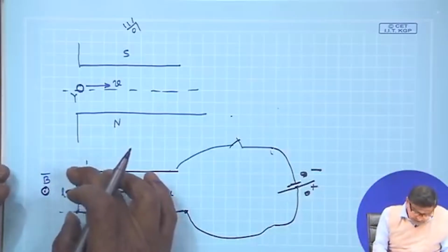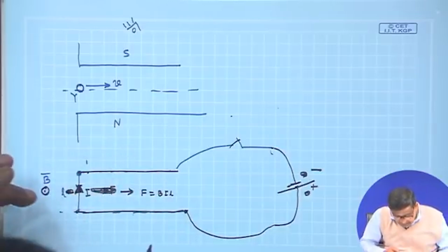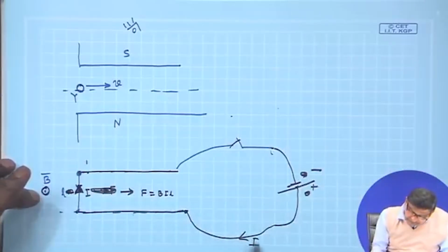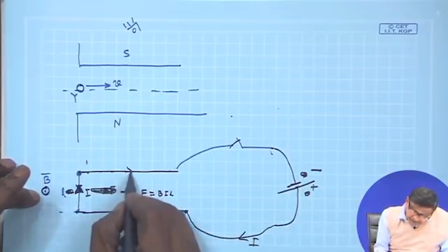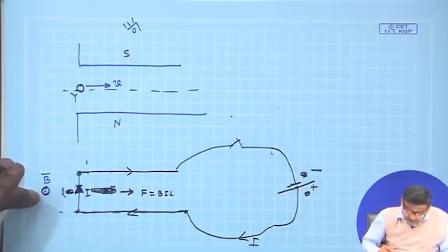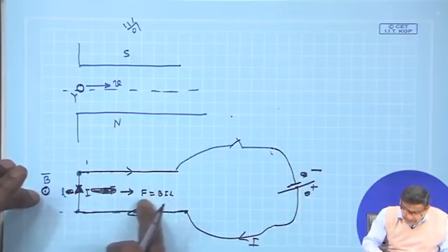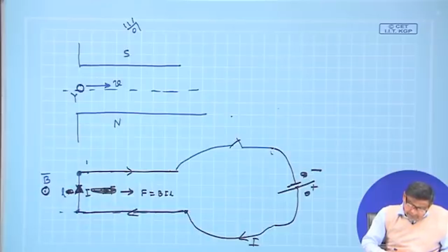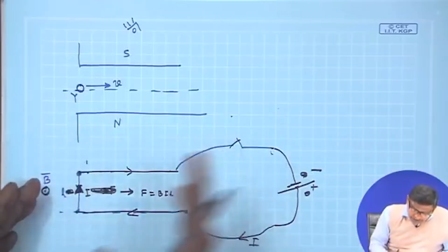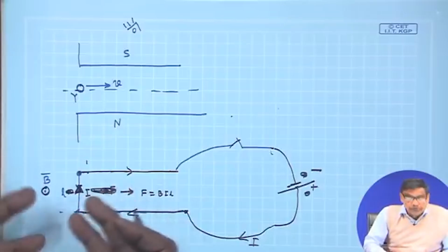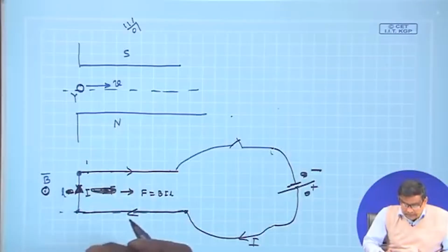Therefore, the conductor was stationary. In the presence of a magnetic field, you pass some current I, it will flow like this through this flexible wire, it will complete its path, and then it will experience a force B I L. Now, as it starts moving, if you apply some force to a mass, it will accelerate.